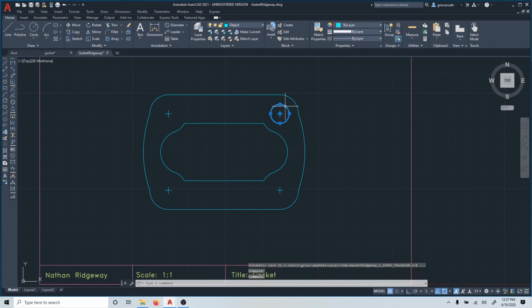And I can either select Control C, Control V for our next circle. I'll have to place it, select it, click the move tool, mouse over the edge of the circle to show the center, and then select the center, which would be a circle. And now I can put it onto the center, which will be a triangle. Or, easier, I can simply go back, select, and just draw these each individually.